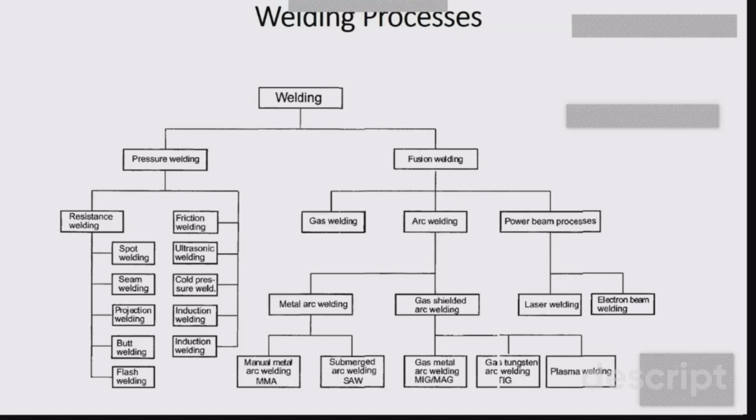Therefore, this tungsten inert gas welding is used for the welding of thin workpieces, and it is primarily used for the autogenous welding process. But sometimes, if the workpieces to be joined are very thick, then additional filler wire is also required that you feed into the heated zone from the sideways.